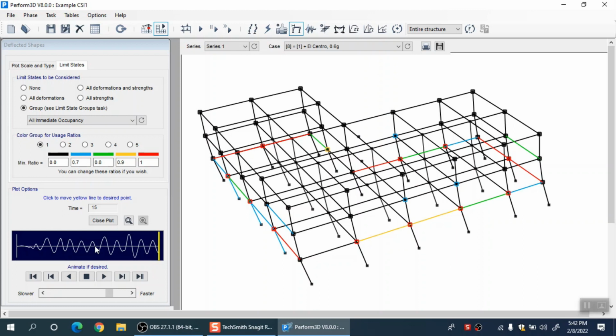For example, if a concrete is designated as 30 megapascal, there will be a factor which you apply on that 30 to convert the nominal strength into expected strength, right. So, expected strength may be 35, 40. Similarly, for Fy, if 60 ksi is the yield strength used by the code based designer, in PBD you may use 70 or 75, there will be a factor associated with that, and there are different performance based guidelines which give us these factors.